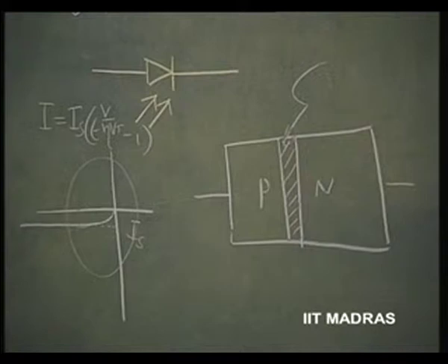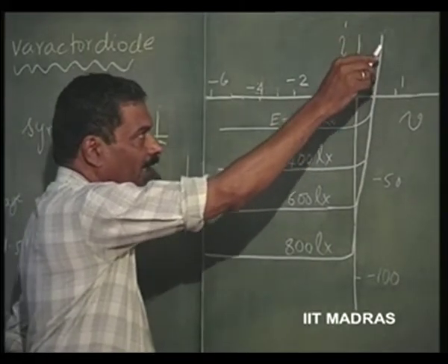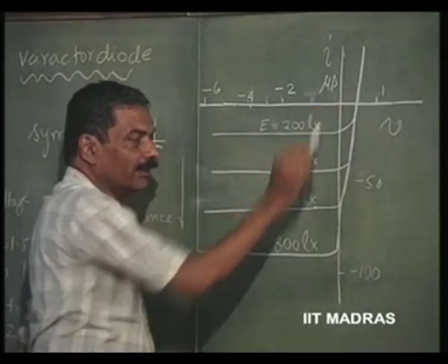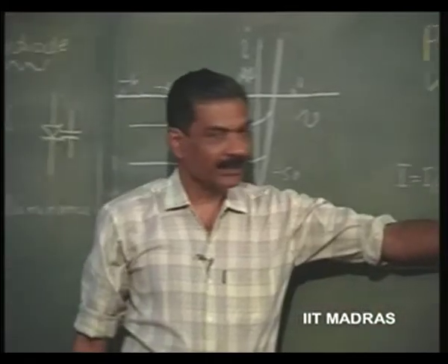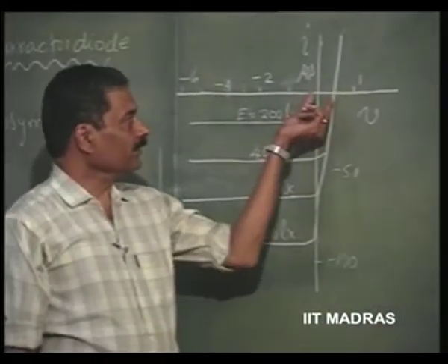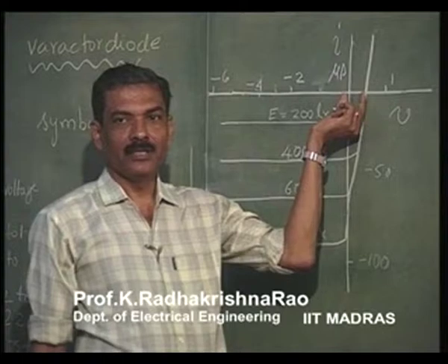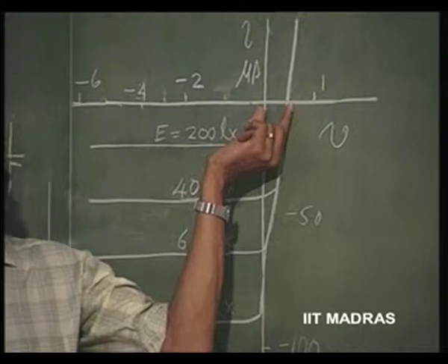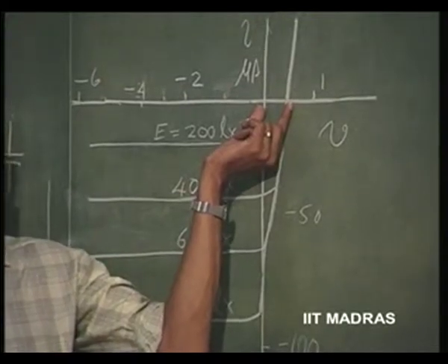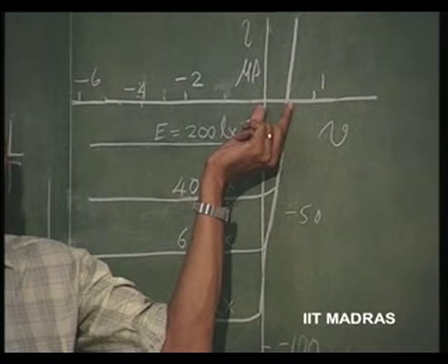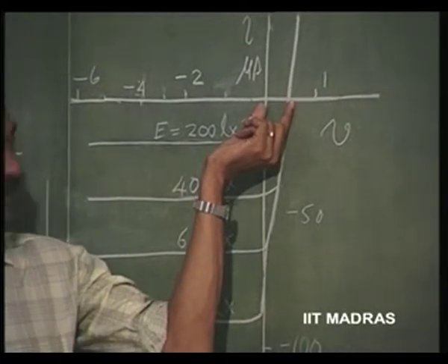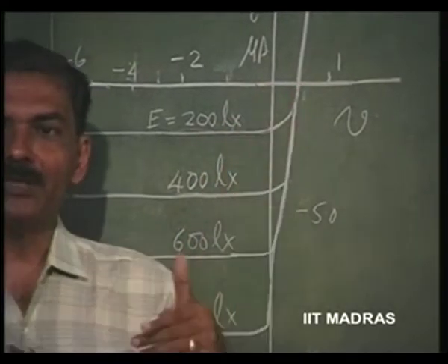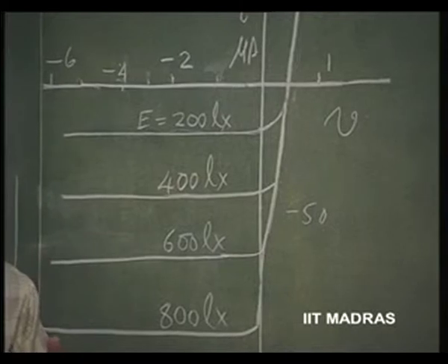So, this particular diode characteristic now will be like this. This is the reverse saturation current saturating here. Not only that, because it can be sustained like this, it is going to have an open circuit voltage, because this current is 0. This open circuit voltage, if the intensity is large enough, gradually goes towards the 0.5 V value for silicon. So, this is the open circuit voltage, and therefore, it can be used as a voltage source, a battery.